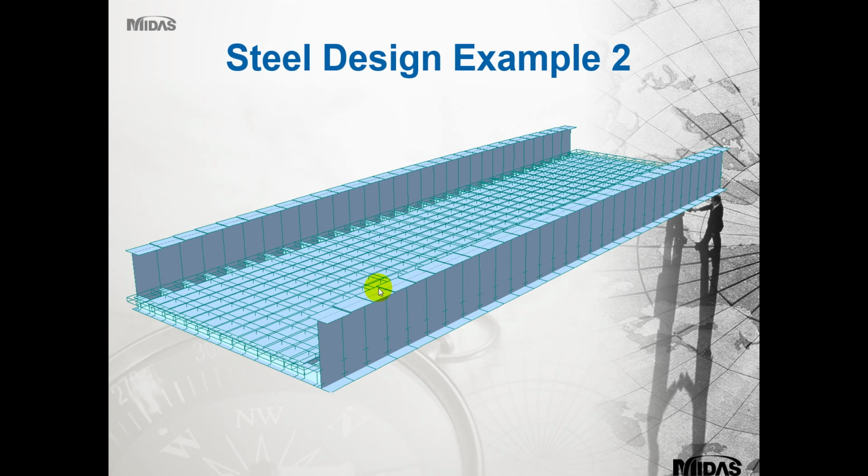So now just going back into the presentation. So this is the next bridge that we're going to focus on, and these are the main girders, and these are the more common practice in the UK. So you've got your main girders, you've got your cross girders as well, and this is where the stiffener plates will come in for the buckling effect. So when a vehicle goes over it, if it is at its centre span, which I'll indicate with the mouse, so say there was a vehicle there, then buckling can be created in the main girders to the side where they will tilt in. That's why stiffener plates are used to hold back the forces and the moments that are actually attributed to the sections.